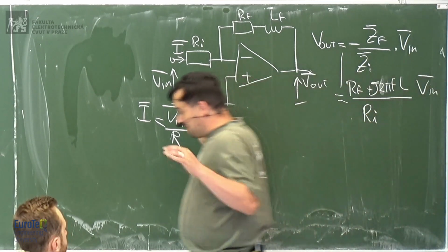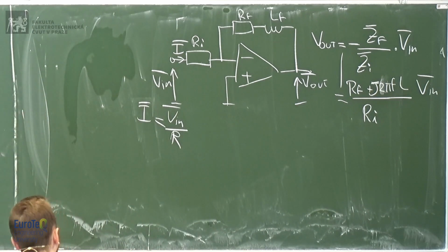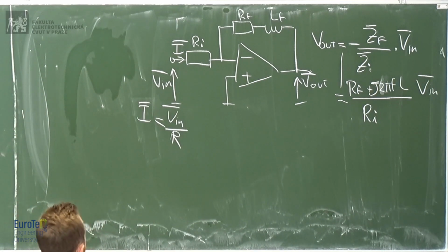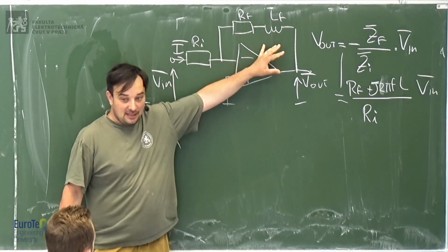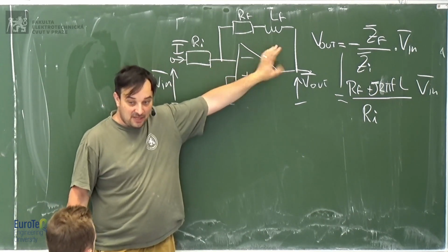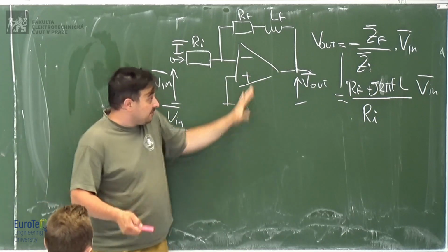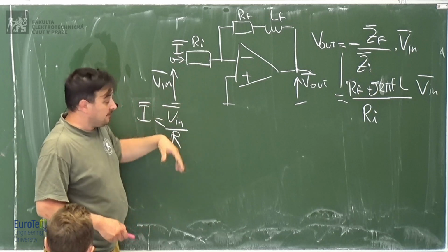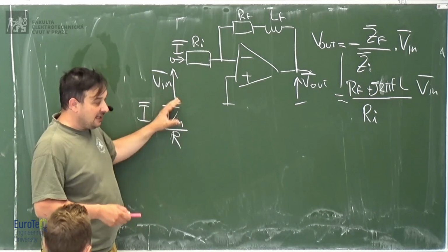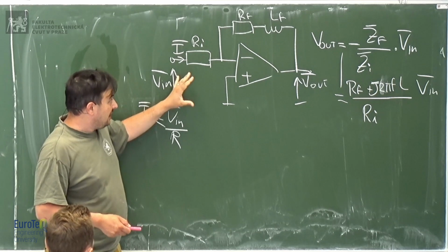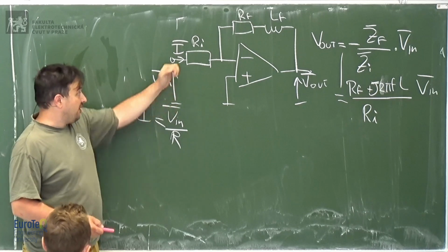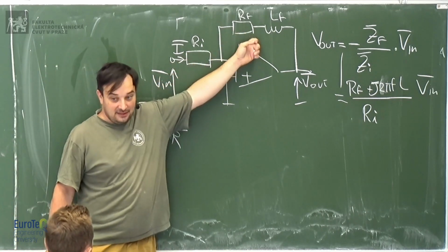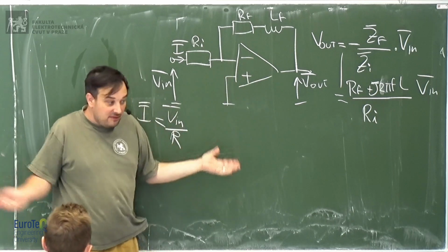And then if you have a capacitor, it's the very same thing. So don't be scared if you see something in AC where there are not only resistors but also inductors and capacitors. You apply the same rules, but you just change the numbers into complex form. Instead of having real numbers, now you have phasors. Instead of voltages as real numbers, you have phasors of voltages and phasors of current. Instead of the resistance, you get the impedance. But everything else is absolutely the same.